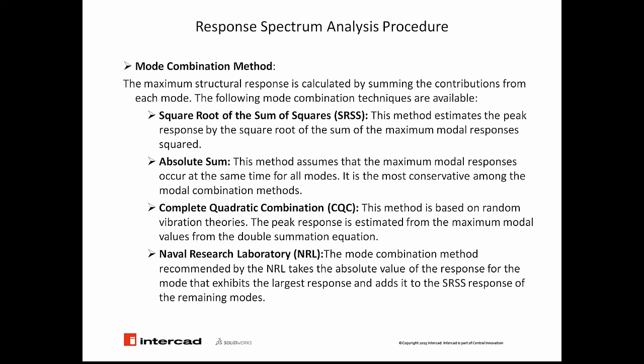But one thing for sure, what we understood up to here is we have a system, and the system has its damping ratio, stiffness, and mass. The peak response of the structure to a base excitation is what we are going to apply and measure, and then for different modes of frequency, those peaks need to be added together to get the new response. That is what is required for response spectrum analysis here.